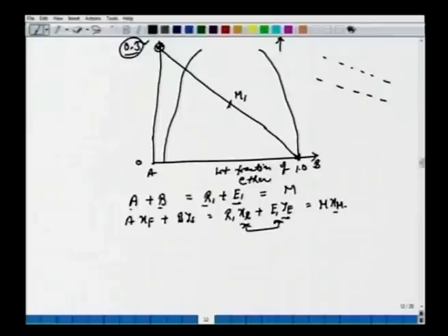So we know these compositions here and here. Here we have plotted X versus X and Y versus weight fraction of ether. We can solve mathematically or graphically. We have points 1, 2, 3, 4, which are all known, given to us. X_R and Y are not given to us, but we know they are in equilibrium, right? So two unknowns, two equations. We have to calculate this X_M.